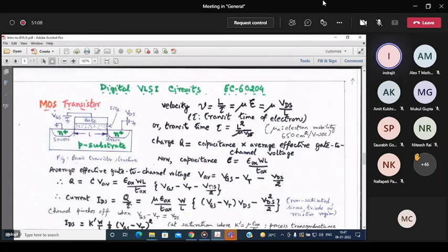Acha. Next. Again, today, as we are in a mood to recapitulate these things, just recall how you build up a basic NMOS transistor. So we have an underlying P substrate. This is important from the point of view of mechanical support as well as providing the ground for MOS electronics. Okay, metal oxide semiconductor.